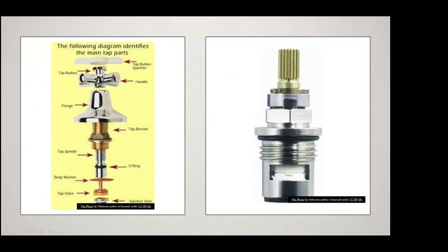These are your old-fashioned tap works. So this brass bit here is called the jumper. Sometimes they're plastic, they're usually brass. That's the washer. That will screw down into the body and the seat. The water comes from underneath. Then you've got a body washer. That's sitting up there on the main body, sealing that up. And then the internal O-ring. So that's sort of the main bit. That's what stops all the water squirting out by the handle, so between that and the body washer.